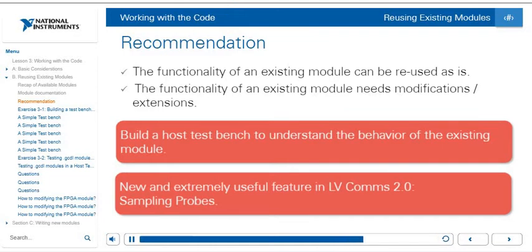We also highly recommend leveraging a new feature in LabVIEW Communications 2.0, which is sampling probes in your simulation, which gives you the value of different wires on a basis of the actual clock cycle as it progresses over time.